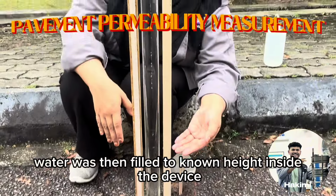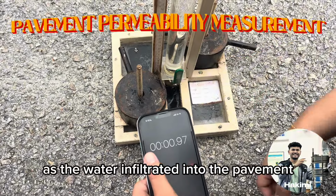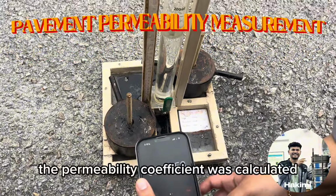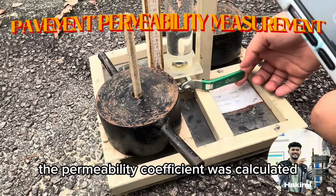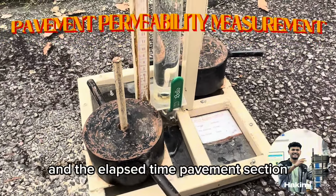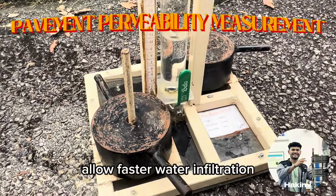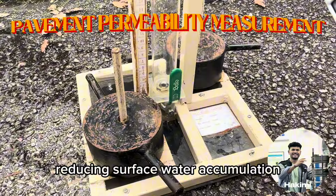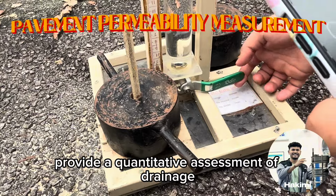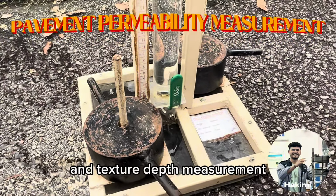Water was then filled to a known height inside the device. As the water infiltrated into the pavement, the drop in water level over time was observed and recorded. The permeability coefficient was calculated based on the change in head and the elapsed time. Pavement sections with higher permeability values allow faster water infiltration, reducing surface water accumulation and hydroplaning risk. These tests provide a quantitative assessment of drainage performance, complementing the skid resistance and texture depth measurements.